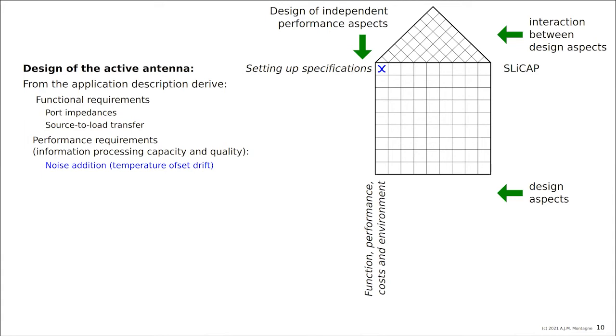But in many situations, typically in this situation with the active antenna, we are dealing with frequencies of interest that are much higher than the frequencies where we have temperature variations. So we don't have to pay much attention to this topic here, but if you want to make so-called DC or low frequency amplifiers, it can be very important to take this into consideration.